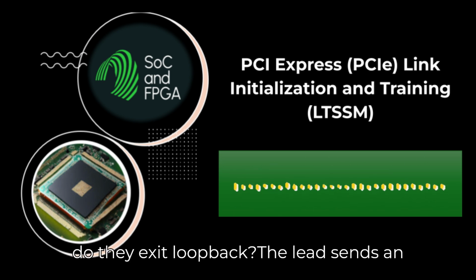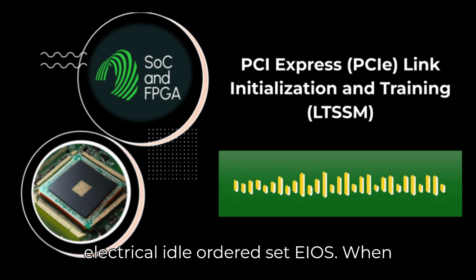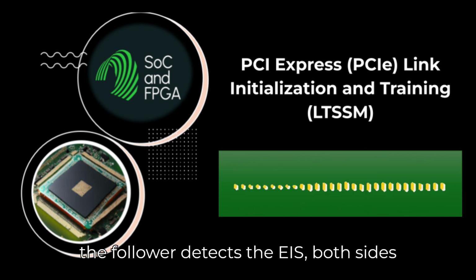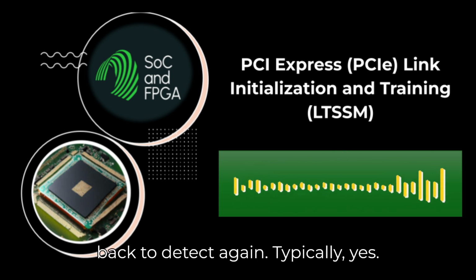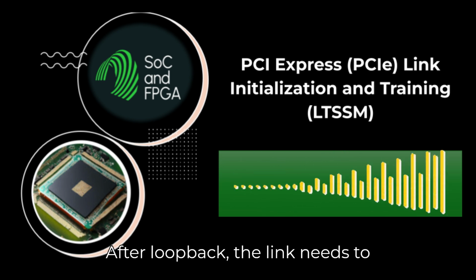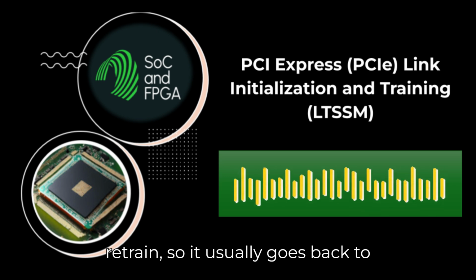How do they exit loopback? The lead sends an electrical idle ordered set, EIOS. When the follower detects the EIOS, both sides exit the loopback state. And after exiting, back to detect again. Typically, yes. After loopback, the link needs to retrain, so it usually goes back to detect.